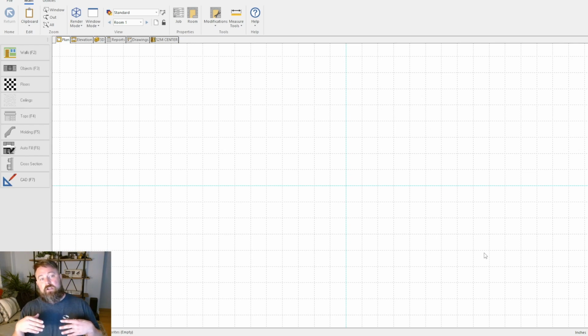And so when you're looking through your reports, you're going to see a quarter, and you're going to be like, well, that's wrong. So if you up your precision, it will all of a sudden change it to 3/16, and you're going to see the true value that is not rounded. So you want to keep that in mind, especially when you start going in and making changes on the back end. If your precision is not set high enough to be accurate, you can get confused at what you're seeing. So all right, moving on from there.